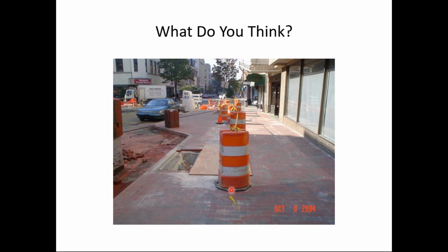But how about here in the center of this sidewalk, these drums, which look like they're maybe six to eight feet apart? That is not a form of edging or channelization. There needs to be some sort of edging here that provides a shoreline on this side of this walkway. And I'm not sure why they didn't have some sort of barrier or edging or channelizer here to keep pedestrians out of this area, because this, to me, is a danger for both able-bodied and disabled pedestrians. I'd want to put some positive separation there to keep pedestrians out of that area.